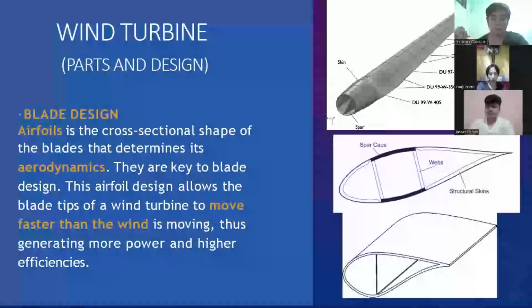Okay, thank you. Now, if you see the cross-sectional area of such a blade, it's reminiscent of what we see in an airplane wing, wherein when air hits this, it produces a pressure differential, making the air that goes on top of it flow faster, while air that goes below it flows slower.